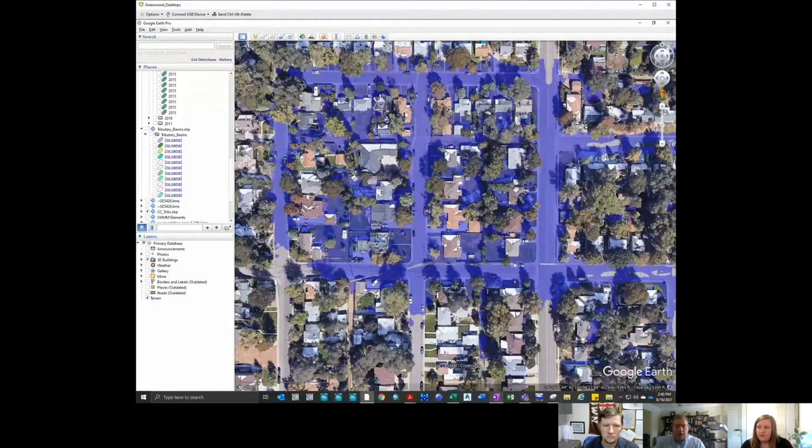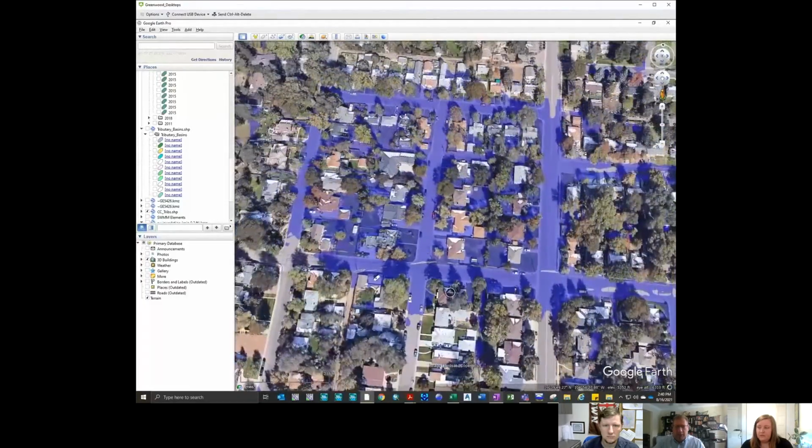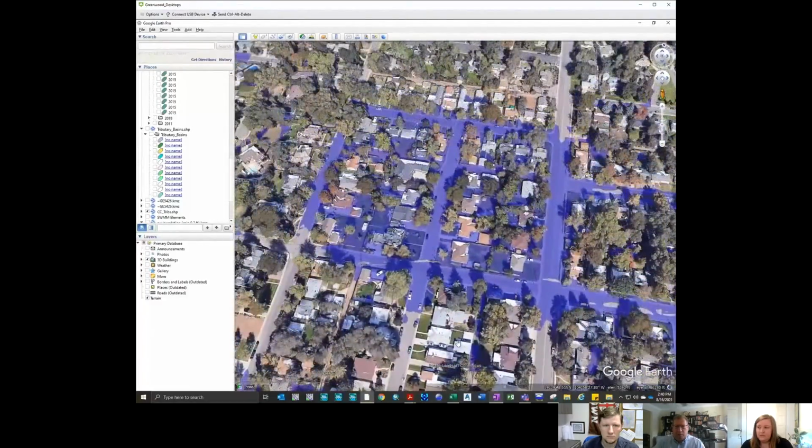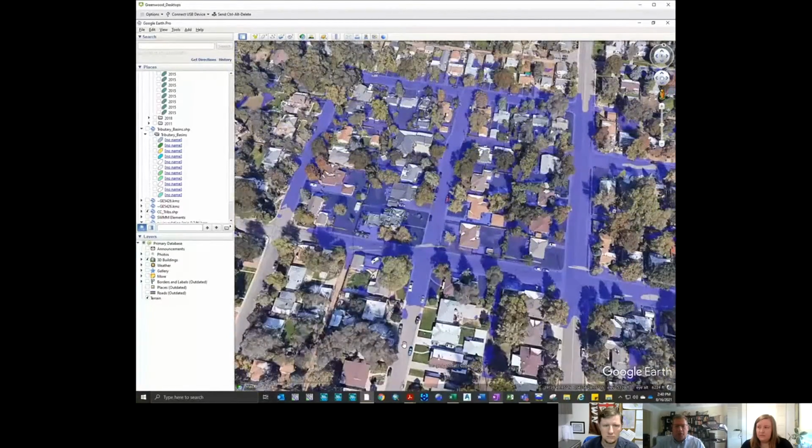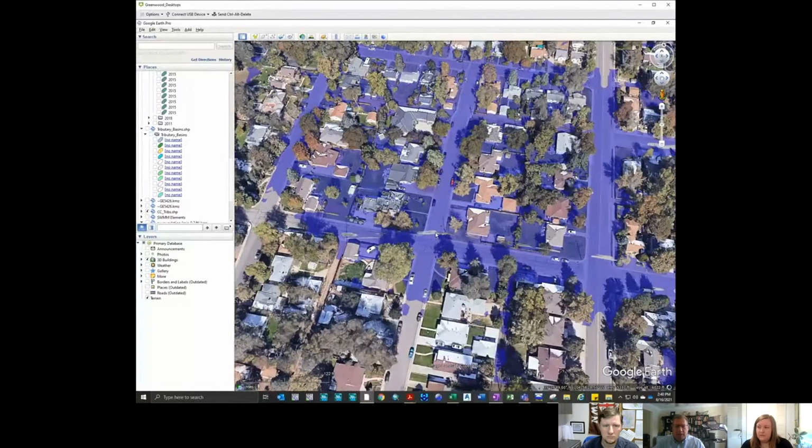This is not caught during normal basin delineations, but it sure feels like this is an area that we want to go farther, identify if this is a risk, and make sure that we're not seeing localized flooding or a depression area or lack of storm sewer.